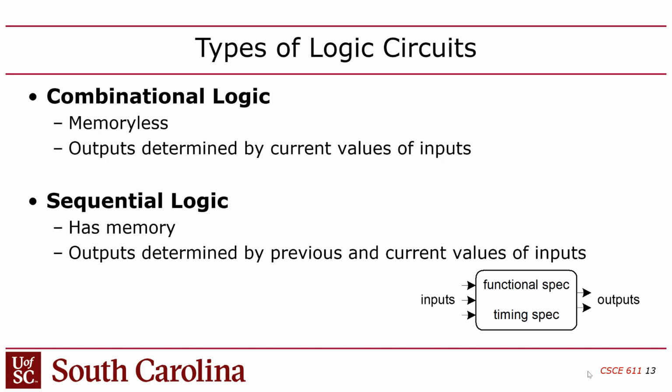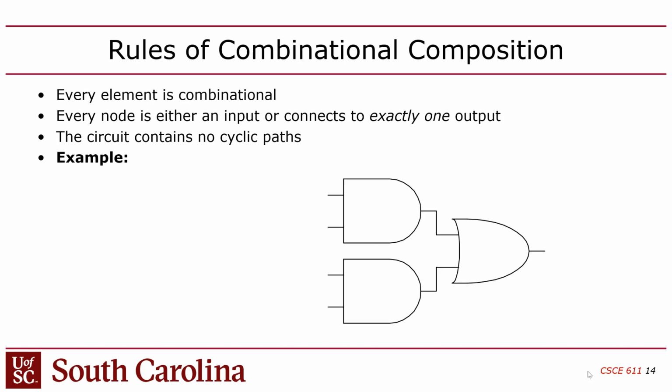And then we talked about combinational and sequential logic. Combinational has no memory, sequential does. In combinational, you have to make sure that you don't have any memory elements in your design. In Lab 2, which hopefully the TAs introduced you to in lab, you're going to be just making combinational logic, and I'm going to do a demo of that as well today and put it on the FPGA. And then starting in the next lab, we'll end up having memory. You might say memory for what? Well, we're building a CPU. We've got to have memory to store the instructions, memory to store the register values, memory to store temporary values, part of the data path registers. And so, we'll very quickly get into sequential designs.